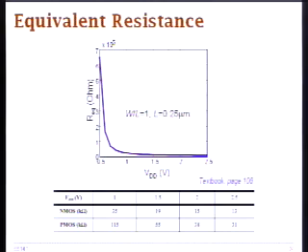a good driver. For values of W larger than this ratio, you have to scale this equivalent resistance by that amount. So you have longer channel, higher resistance, or wider channel, lower resistance. So by making your transistor wider, your equivalent resistance is smaller. And this makes sense because when you make your transistor wider, you have more drive capability. Therefore, you will discharge your capacitances quicker. And you just use that kind of intuition to make sure that you understand what's going on.